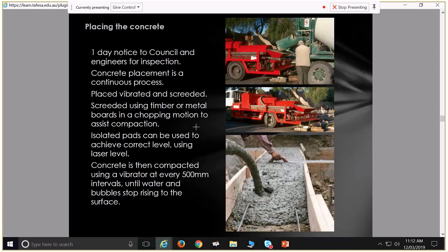Certainly, what you do not want to have is a concrete truck stuck in traffic, because once concrete's all poured together, you've got water in there, it's starting to happen. So time, it's like cooking. Time is of the essence. The guys that are laying it, the guys that are providing it, the guys that are driving it are accountable for the state that it gets there in. So they'll be held responsible if that slump's incorrect.